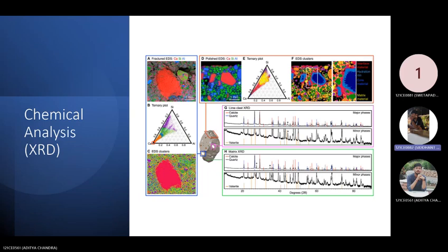And also we can see that the red sample, which is in the left part of that, clearly showing the composition of the calcium is much higher in the red portion. As here, calcium is being depicted with the red one, silicon is the green one, and the blue one is the aluminum. And also with the ternary plot, we can see there is a very minuscule amount of aluminum that is being present in the sample, with the majority part capturing with the calcium and the silicon one.